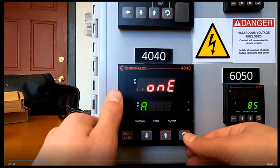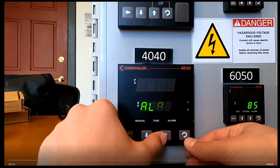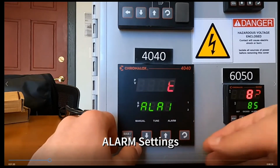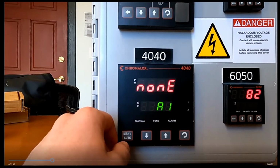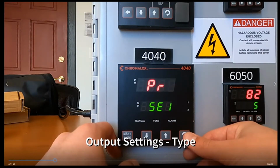And then this is just your alarm one, whatever your alarm output is, you can have that set to be a process high or process low. So you can see here, P high, P low. DE is a deviation alarm. There's band alarms. We can get into that in a little bit more detail, but I wanted to touch on some of the options there and how to get to them. And again, hit that man auto button. When you are in configuration mode, you must hit that man auto button to save whatever setting you just changed.